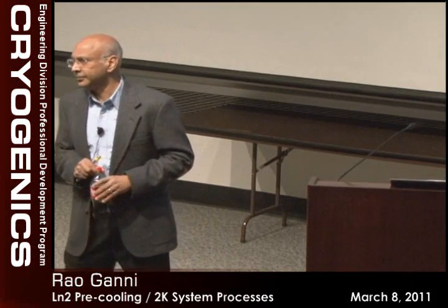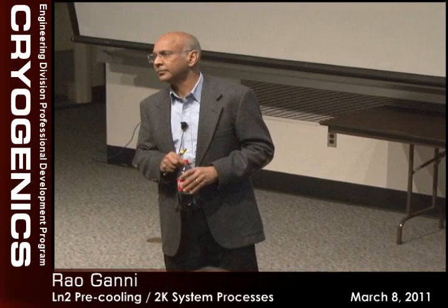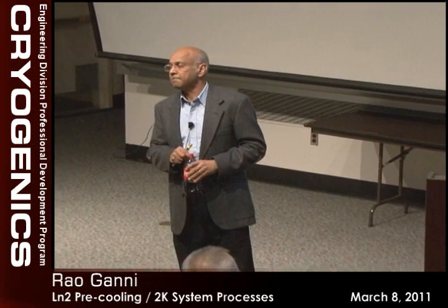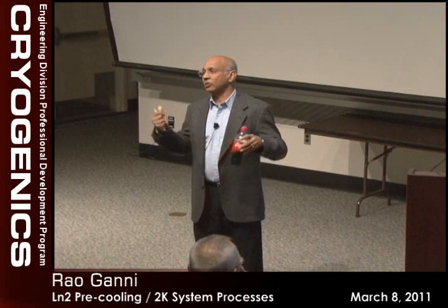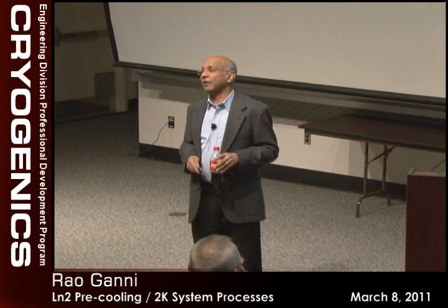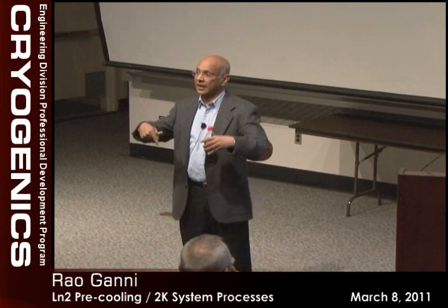How do you avoid helium contamination from oxygen after you pass through your screw compressor? No, all our systems are positive pressure. The leak is out, not in. We do not have any systems sub-atmospheric, so air cannot leak in.